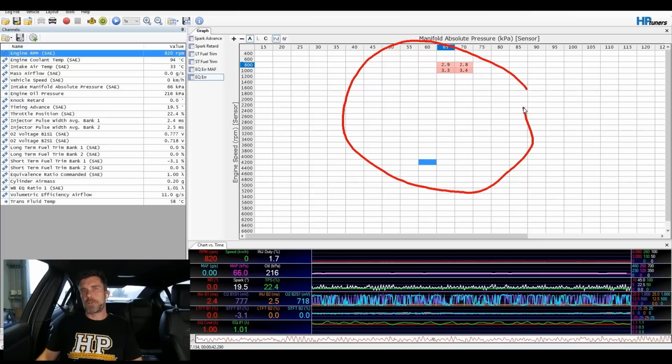I will generally use a bit of common sense here, and if I've got a nice smooth trend to the errors that I've got, and I've got a lot of hits, a lot of counts in each of the cells, then I can trust that data. I'm going to be confident using the paste special function. If not though, if I've got some really big outliers, I would be more inclined to use a bit of manual blending and do the adjustments by hand. It really just comes down to the quality of your data.